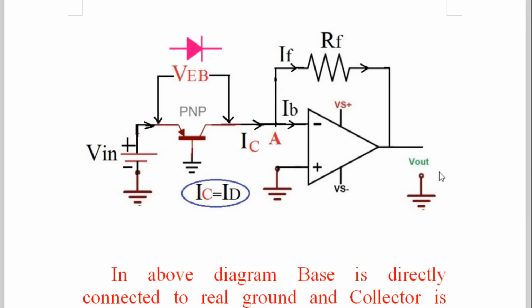We are using the logic of potential difference between 2 points, because whenever a voltage across any component is measured, we do connect voltmeter across that component. And suppose here now you want to measure the voltage between emitter and base of this transistor. Now base to collector junction is short circuited. Therefore, this base terminal appears over here, and therefore it is written as a base. So here you connect the multimeter like that.